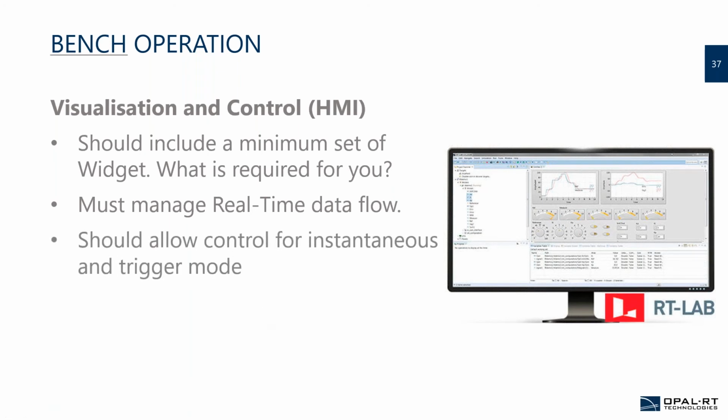Something that we don't talk about but is really useful, especially when you're doing tests, is having a feature that is not just pressing a button, but where you can set multiple parameters in the system and launch the command on them as a parallel command. If you want to set temperature, altitude, and speed of the airplane, you don't want to change them as a human one by one. You want them to start at the same time. So having an HMI that lets you program all of them, and then launch the sequence to send them all together, is really important.